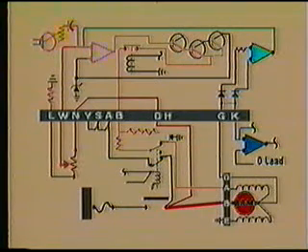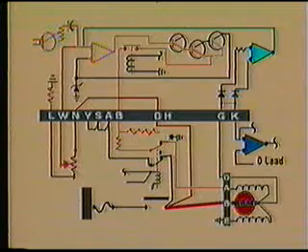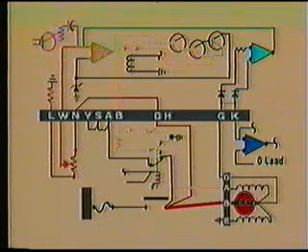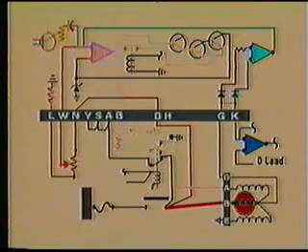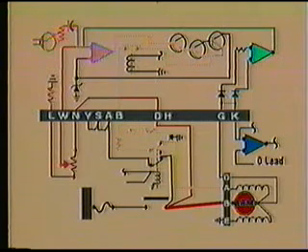As loads are applied to the bus and engine RPM changes, the regulator circuit in each control panel will vary its output to maintain generator output at the desired voltage setting and the sharing of the electrical load between the generators equal.